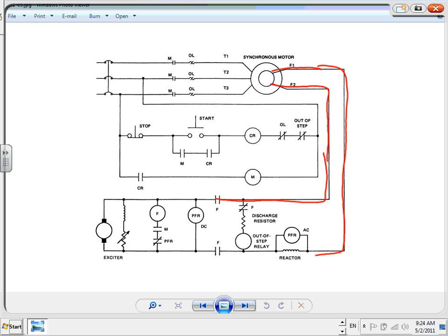And then you have a control circuit. This is the most important thing for the synchronous motor. You have a control circuit here where you can bring DC, you can adjust all these things and put 24, 25, 60, 70 DC volts in the rotor, guys. And by adjusting the excitation for the synchronous motor, believe it or not, this synchronous motor starts pumping, giving kVAR. How much kVAR? Depending upon the size of the motor and the excitation. So most of the time, guys, the motor will be consuming the kVAR.